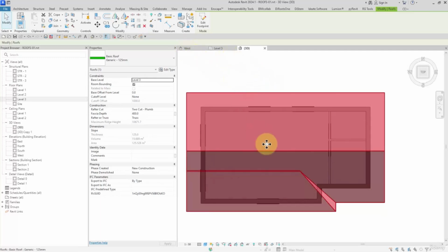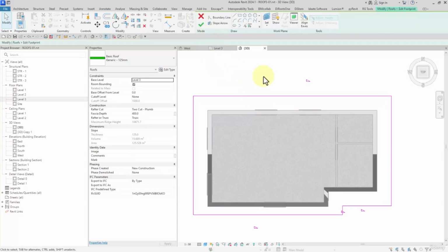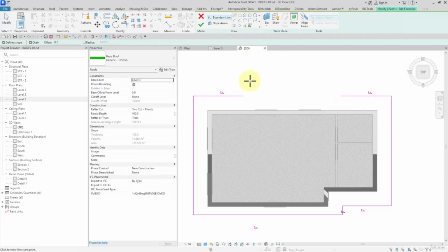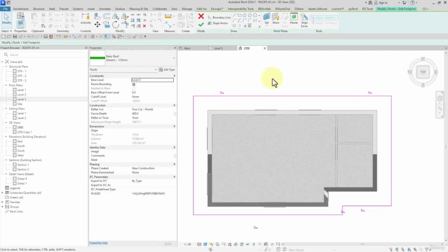firstly we have to select the roof, then edit footprint, then I want to deform the roof. Here from split elements, I check delete inner segments, then I add 2 segments. I specify 2 values, 35 hundredths, and then I want to draw a line which is not sloped, or if it was a slope, please select it and uncheck define a slope.